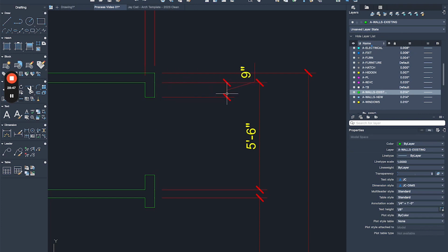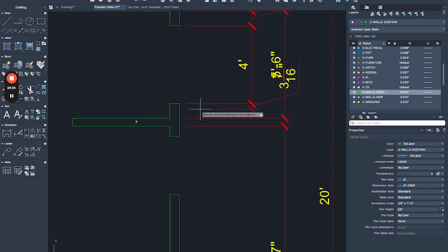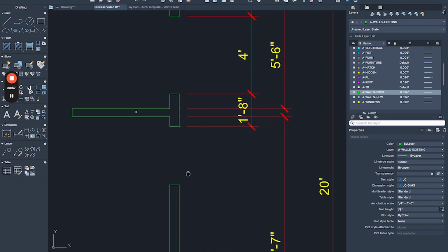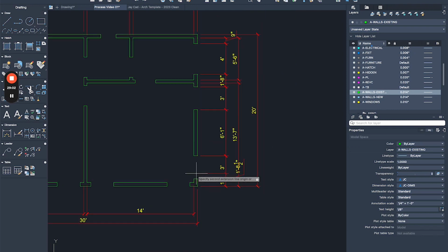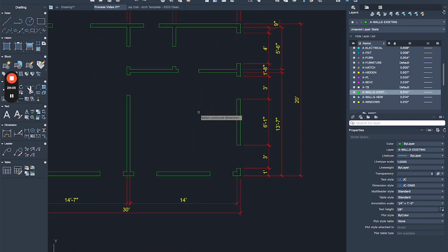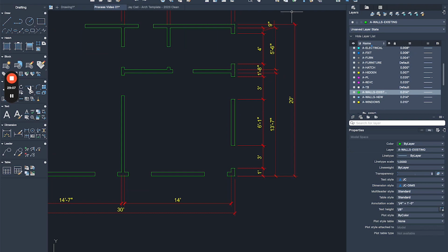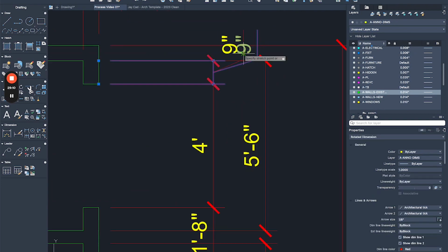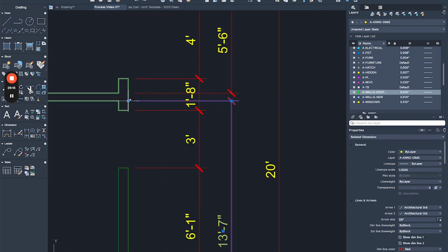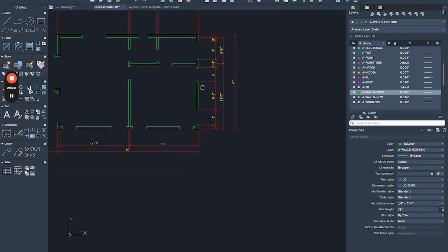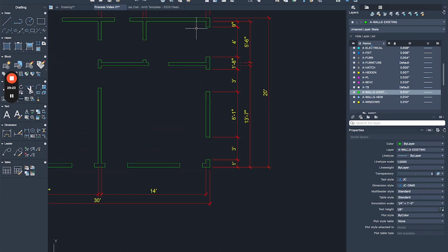So for now, I'm just gonna place this here, but there's a command that allows you to continue the dimension command from the previous point. It's called dim continue, DIM continue. And then that's going to allow me now to just keep going, similar to Revit. I think SketchUp does it this way too, but the command stays active, right? Then I'm going to hit return to finish it, and then I will clean this just to make it like this. And then these openings could be hard to see at this point, so maybe I'll just stretch the dimension out so things are not overlapping, and it's still easy to look at things.